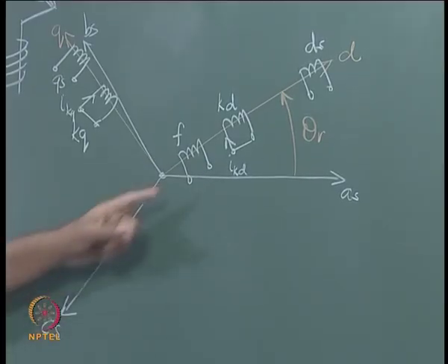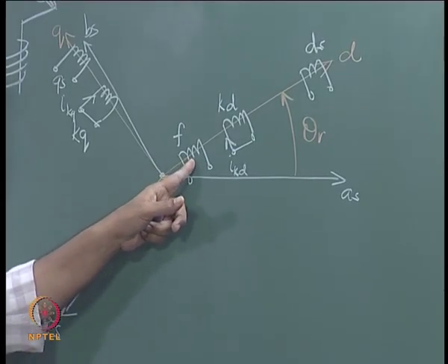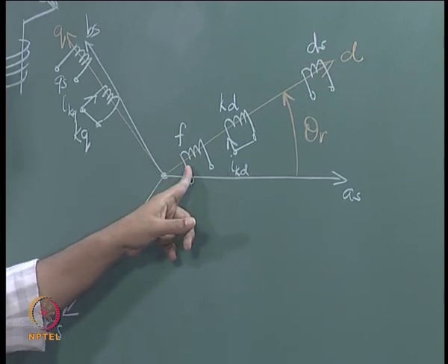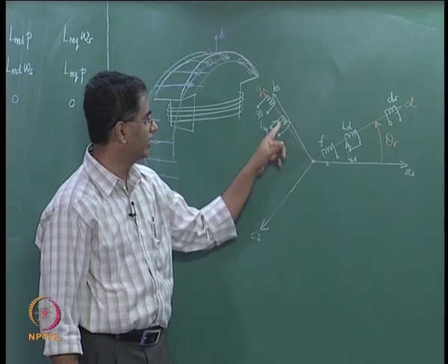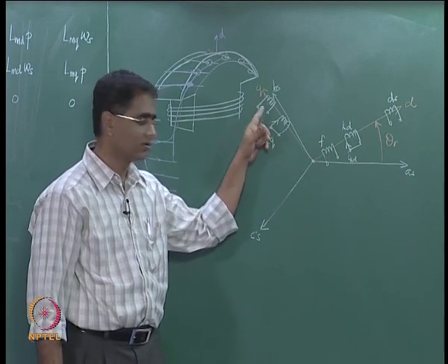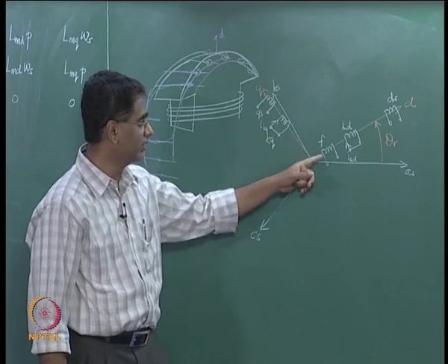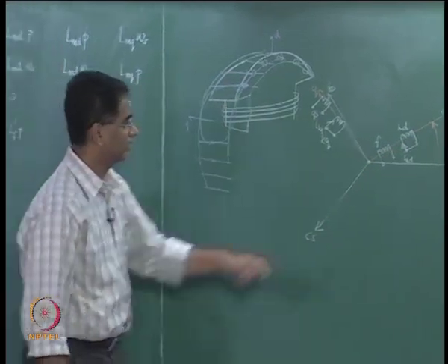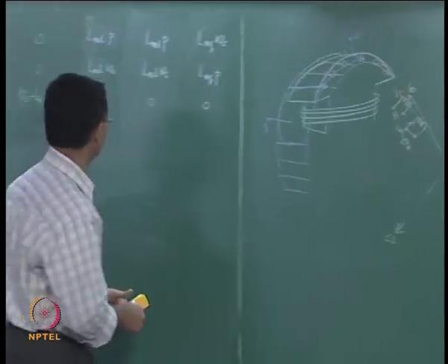So the field coil is actually on the rotor, so it is not a fictitious coil, therefore it will not have speed EMF terms, it will not have di by dt terms due to excitations 90 degrees away, but it will have di by dt terms connecting these two, and of course its own self term which is there.